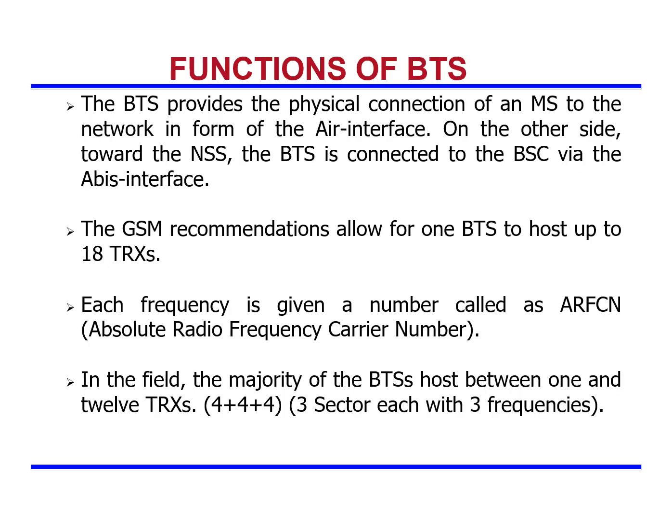Functions of BTS. The BTS provides the physical connection of a mobile station to the network in the form of the air interface. On the other side, towards the NSS, the BTS is connected to the BSC via the ABIS interface. GSM recommendations allow for one BTS to host up to 18 TRX.